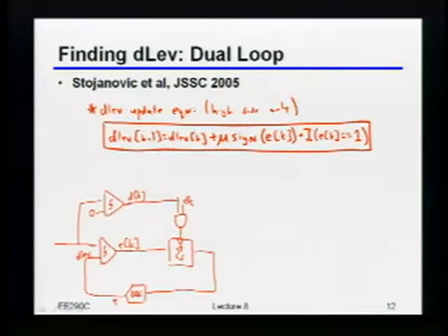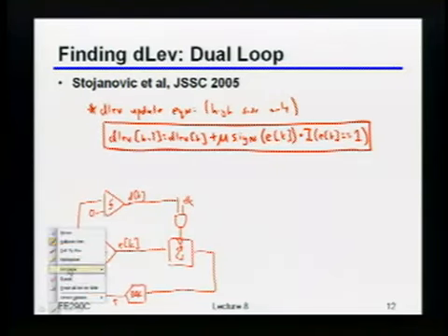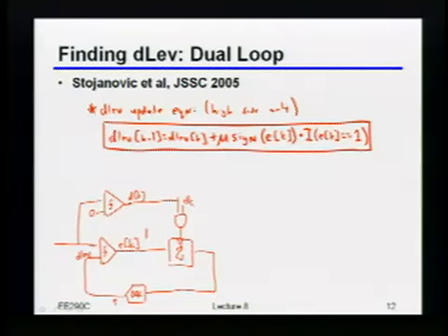You could do something very similar with another loop looking for the lower data bit. But this idea of data filtering is a pretty important one, because we're going to see in a second that you have to play a very similar trick to figure out how to adapt equalizers when you start doing things like loop unrolling. So the key idea is that the way you find an analog level is you look for when the data is telling you that you should be at that analog level, and then you filter your updates based on that data pattern. Okay? Does this make sense to people?